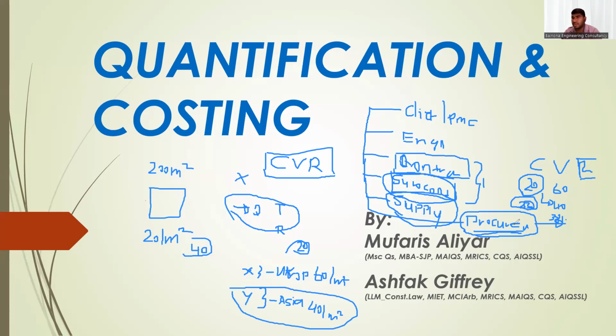Then after the defect liability period, one year or whatever is mentioned in your contract, you have to do the final account. At the end of the final account, you have to submit the discharge letter and claim your final amounts, including your final retention. So these are all the contractor's quantity surveyor duties in the post contract.